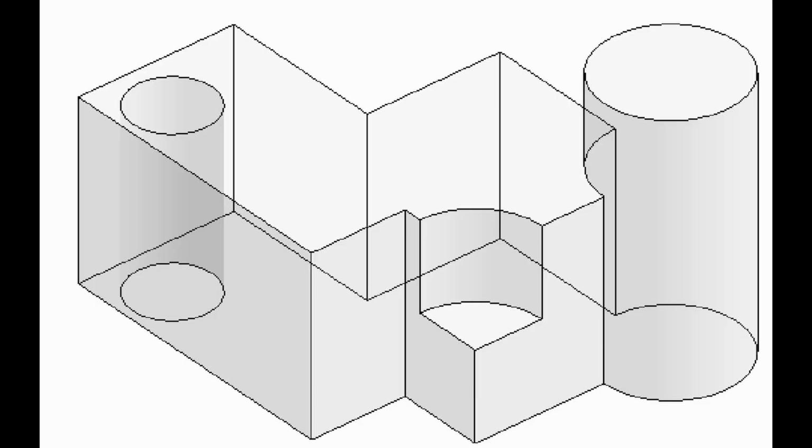In this session, we focus on the different types of geometric forms available in Revit, the foundational shapes that lie behind every hosted family, every system component, and every custom object you will ever model. The purpose of this module is to understand how these shapes work, why they behave the way they do, and how to apply them when creating project-specific geometry, especially when standard family templates are not sufficient.